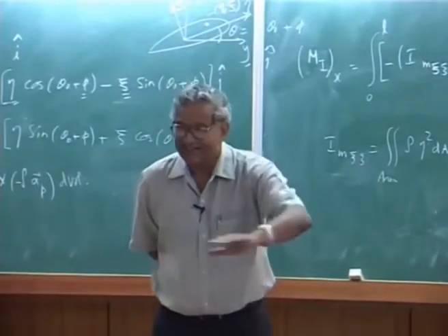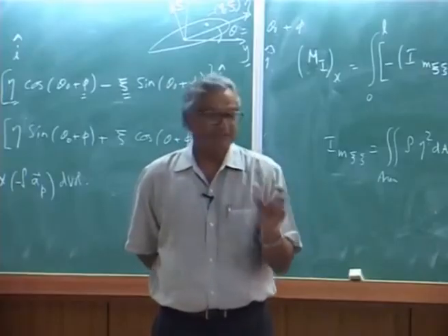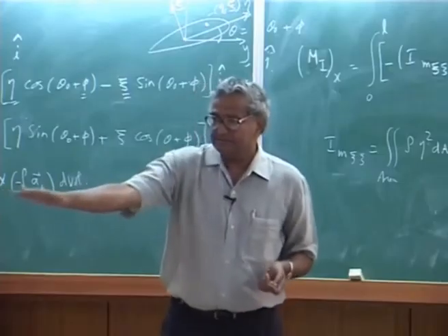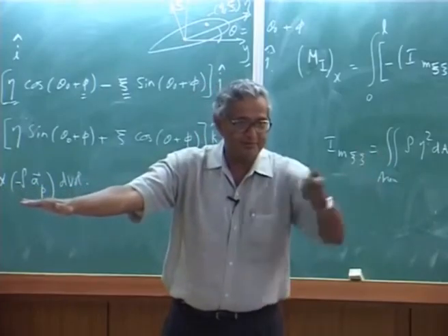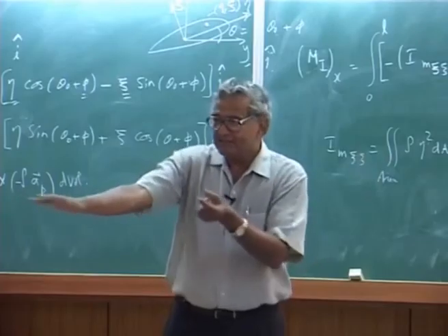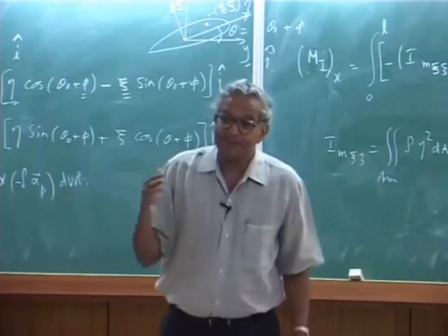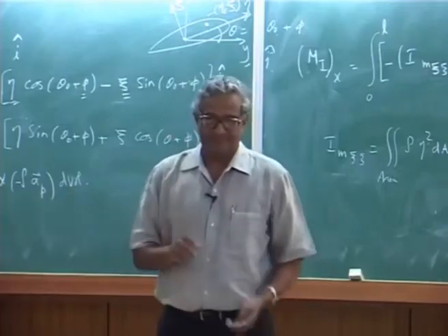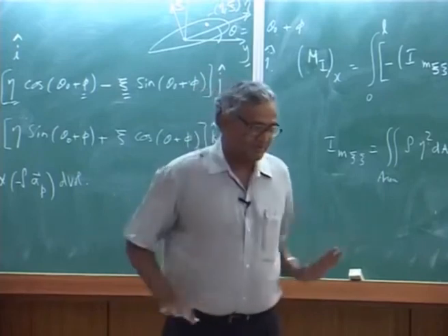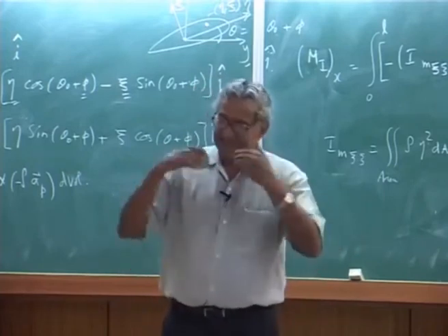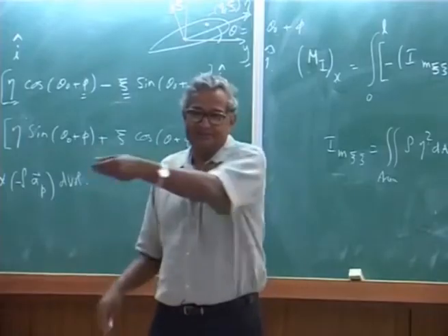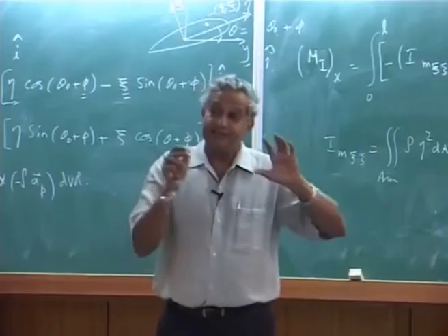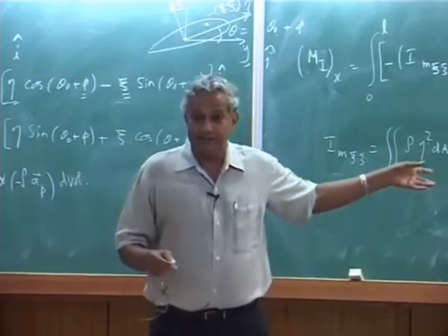When you talk about lead lag, I never expressed any aerodynamic term for lead lag motion also. You are having the blade moving like this, the flow is coming. That means it is a pulsating flow. You want the drag force in a pulsating flow. Okay. We do not have expressions for those things. Later we will make a lot of approximation, and that is why we will say, okay, this is the aerodynamic load. That is why I did not put any aerodynamic expression when I derived my lead lag motion.